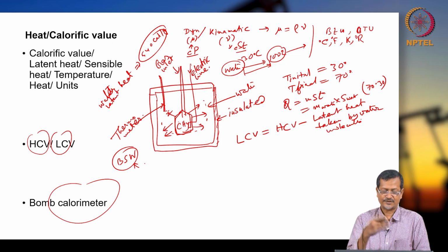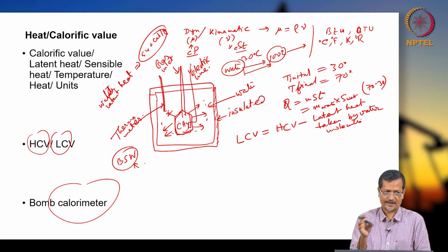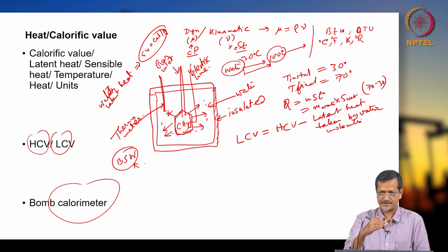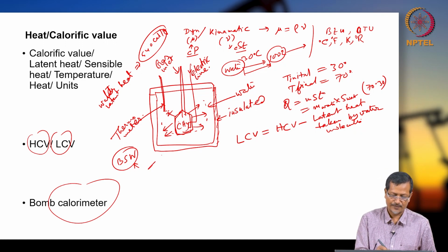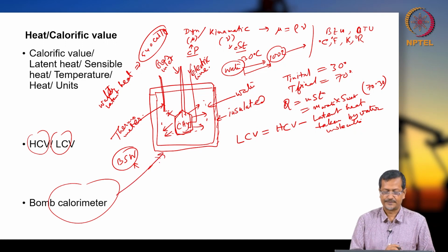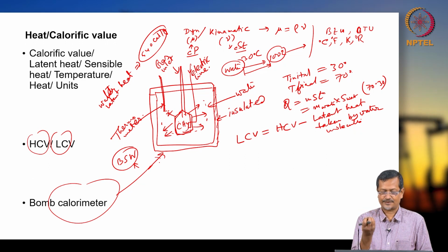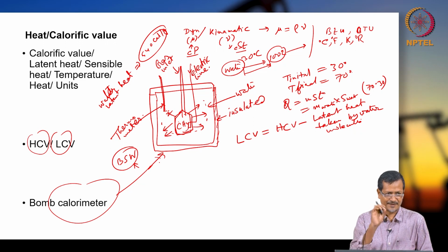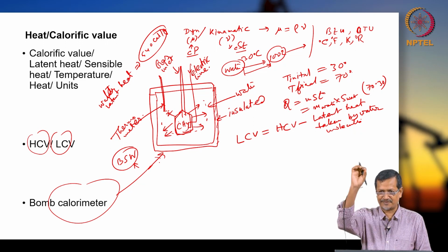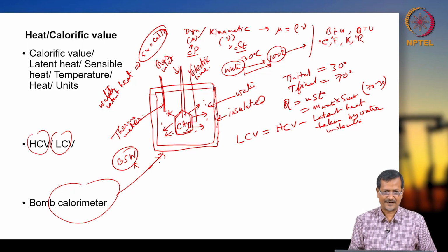If you have more than the certain amount, they will not buy, so you have to ensure your oil or gas is below that specified limit. This calorimeter is called a bomb calorimeter. You are creating a small bomb blast, and that heat increases the temperature of the water. Now measure the water temperature, initial and final, and the total volume. Finally, you can calculate how much heat you got.